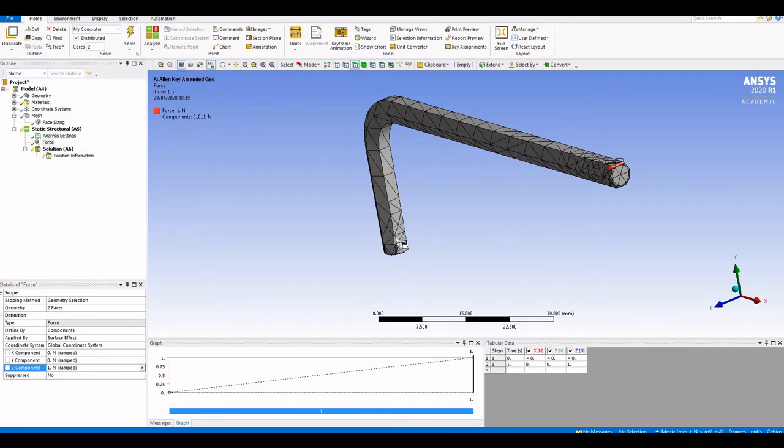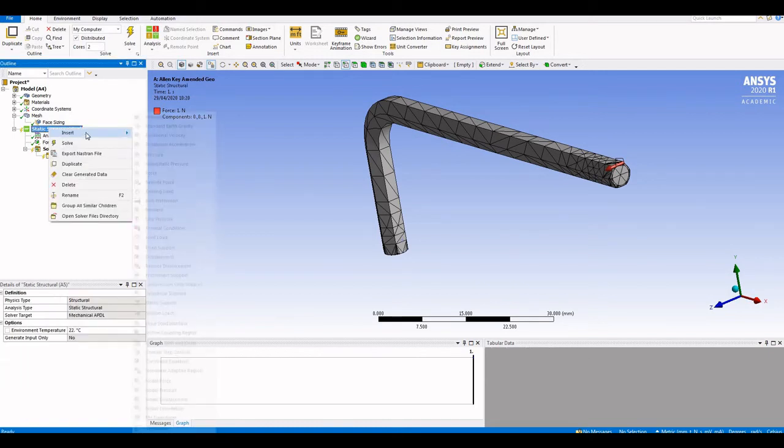I'm going to assume that this Allen key is held on its edges rather than on the surfaces, because I personally believe that when you twist it, the edges interface with the edges of the bolt, the slot, and those edges carry the highest reaction force. For that reason, I'm going to assume worst case scenario, and I will apply my boundary conditions on those edges.